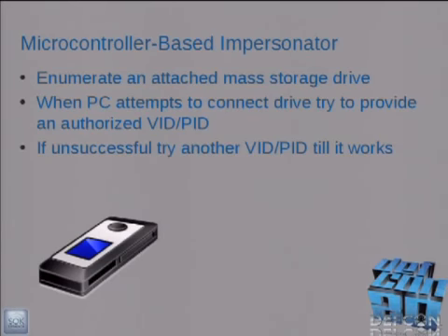Right? If it's not successful, it tries the next one. All right, so there are 2 basic modes of operation in the device. You can either say, oh, well, I know what the VID-PID is, and I'll just set it, or you can try automatic mode. In automatic mode, I have 500 of the most common VID-PID combinations, and it will just scan through those.